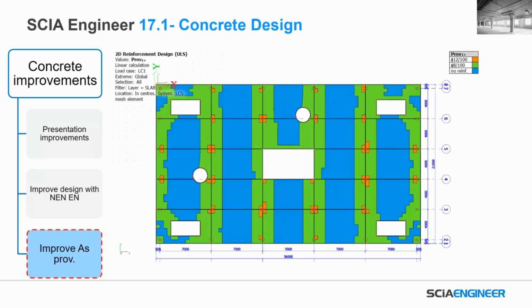Now what we have is maybe the data shows a little bit less on the slab itself, but it makes a lot more sense practically for how this is being shown, how you would model it. You can see here we're maybe putting this reinforcement in strips, and we're only adding additional reinforcement around the columns in this case, and we don't need reinforcement in those middle strips as opposed to those column strips. So really the idea is to take the results from a finite element analysis and allow you to better get them to the point where they need to go on your drawings or into your model.